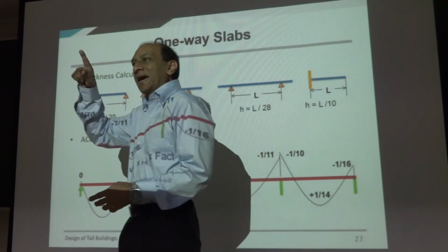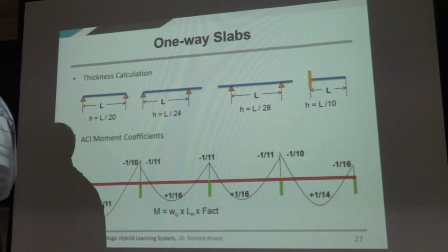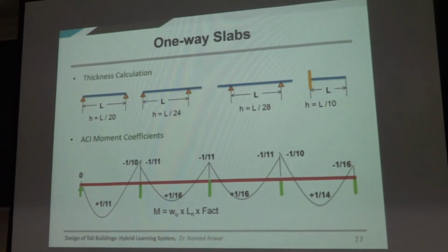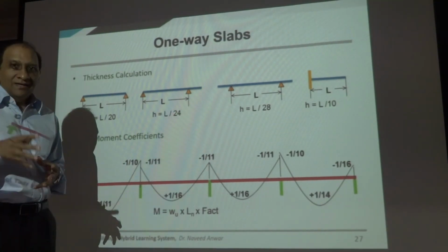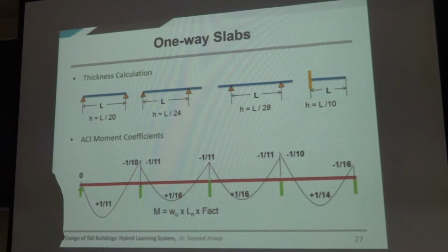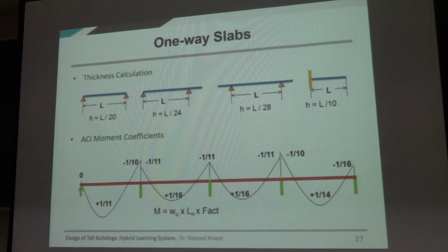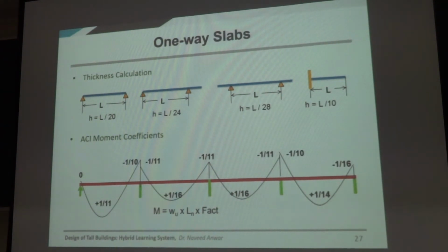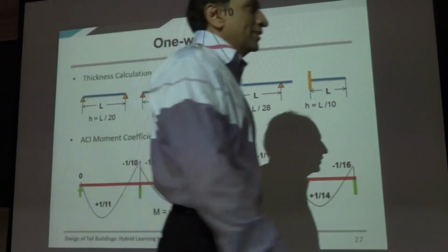So there is going to be an enveloping of the bending moment diagrams because of the alternate live load patterns that you did not consider in ETABS, which should be considered according to the code and other codes. So you must consider alternate live load patterns, many of them, 5 or 6 of them, before you can come up with the moment diagram, and you must consider the envelope of the two. So you basically get moment envelopes. What is a moment envelope?